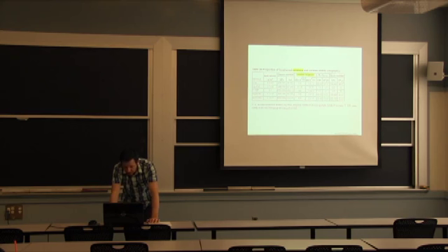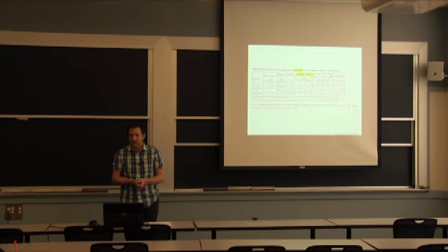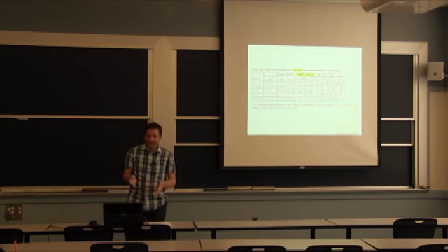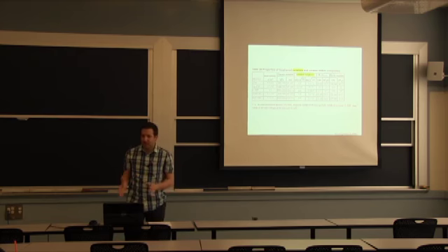So here we're looking at these stabilized systems, and we have the magnesium partially stabilized zirconia, where we have this fracture toughness between 11 and 14 megapascal square root meter. Now, these are not design allowable. These are, you do the experiment and you get this range of data.